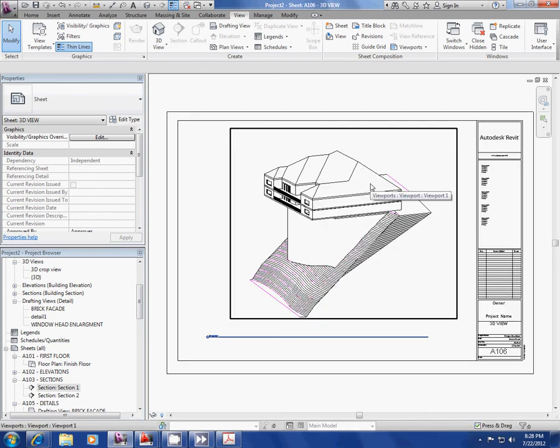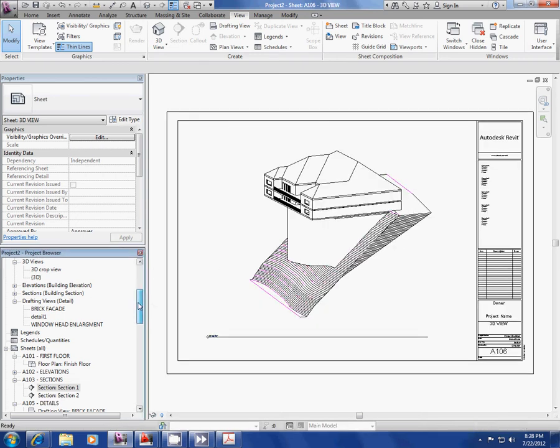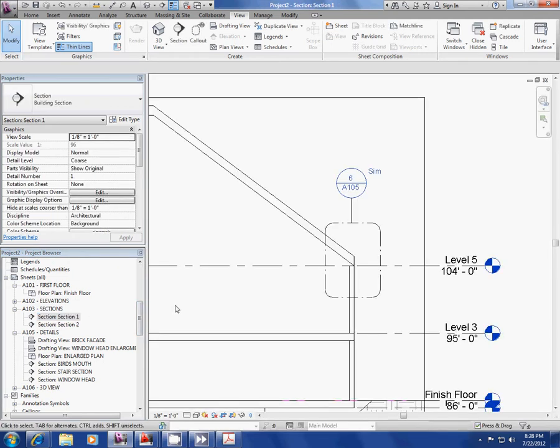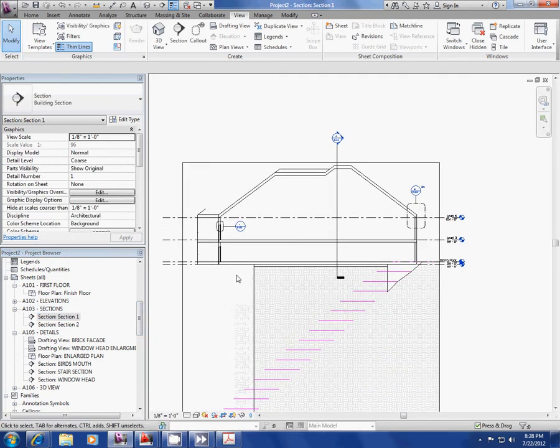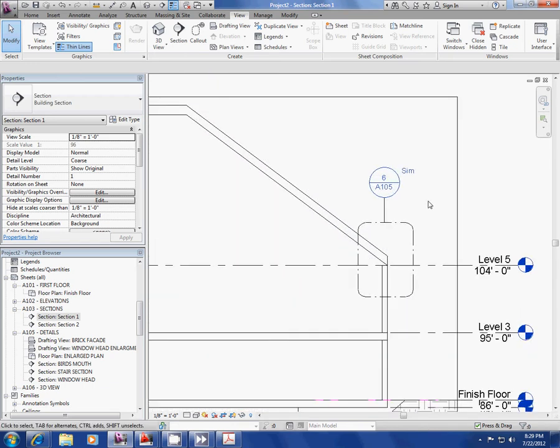We'll talk about... So just to add a little idea, since our model is drawn in 3D, and we're referencing this point where the two pieces collide, and we're referencing a detail that has been drawn already, super detailed. So that's kind of a workaround way that you could call out certain parts of your model by referencing more detailed drawings, and this is the way you would do it. So essentially, this call out is not referencing this particular area in the model. It's actually being connected to the detail that we imported.